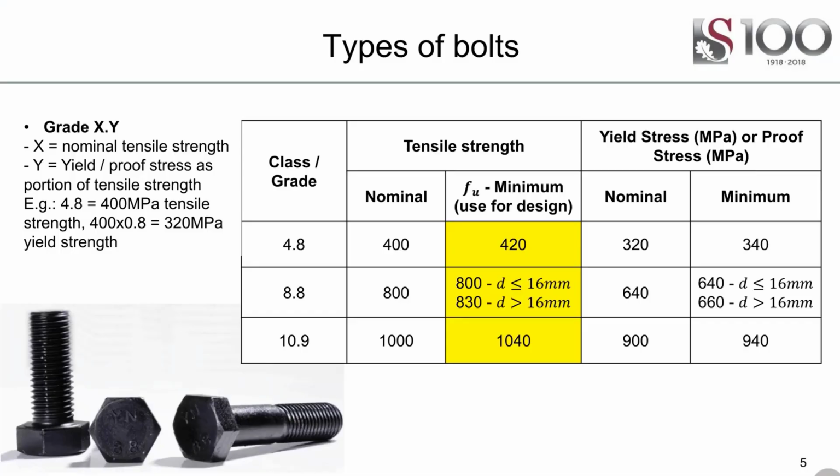So when it comes to bolts and bolt connections, we firstly need to know what is the grade of the bolt. And you've got three main grades: 4.8, 8.8, 10.9. The most common for structural use is 8.8. So if in doubt, go with 8.8. However, in reality, in many situations, 4.8 is probably sufficient.